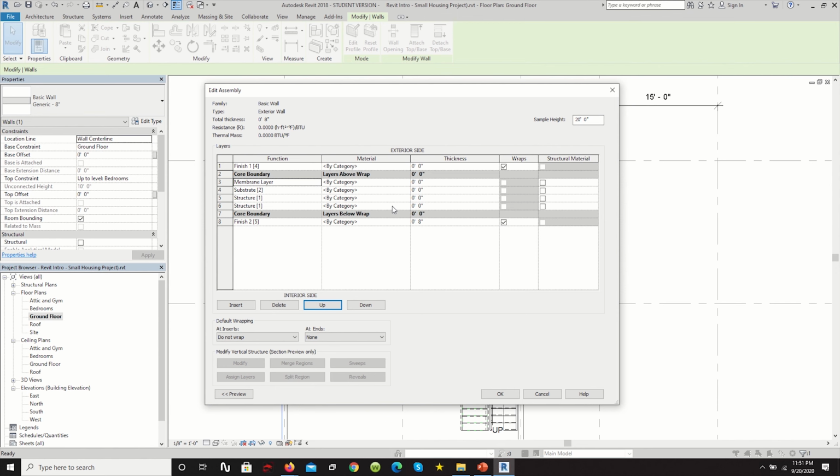And then we're going to have our, oops, let's change this back to thermal air. And then we have our structure, like our studs. And then you can have things such as your interior finish. In some cases, you have other components. We're just kind of looking at this as a very generic wall structure. So let's say our exterior finish is somewhere around 1/2 inch for our paneling. Let's make it that. Let's make our membrane. Our membrane is going to be so thin, like not even a 32nd, like a 64th of an inch. So thin.